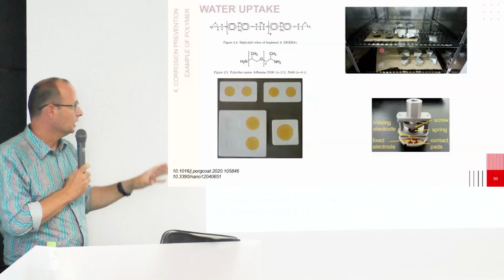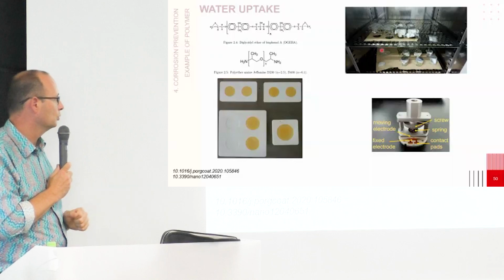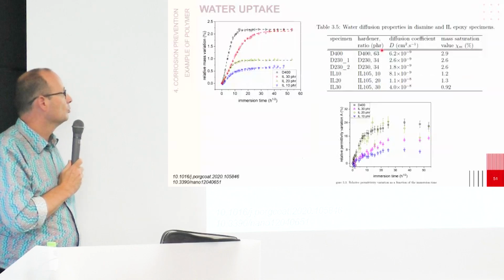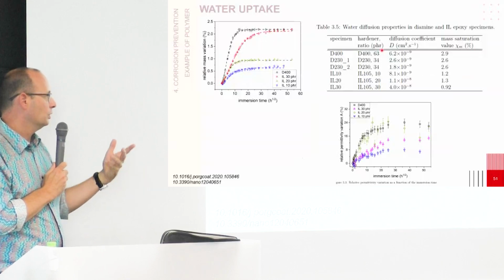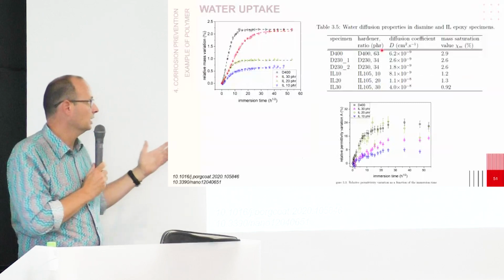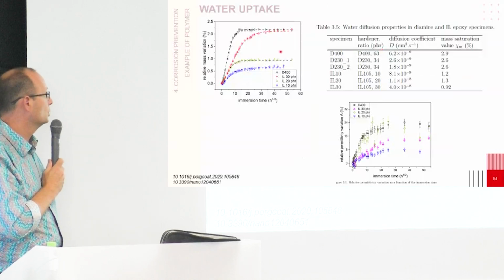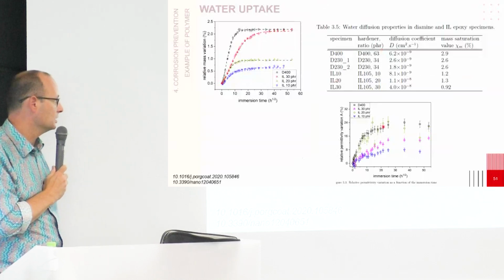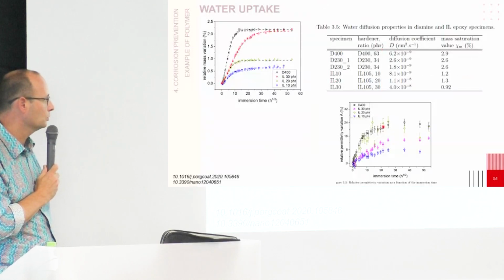In this case, it was capacitive measurement, so using the evolution of the dielectric properties of the polymer. What were the results? So here the question is, can we have a reliable technique to evaluate the water quantity in the material? The first graph, which is on the top, is a mass evolution of a coupon. And at the same time, our young colleague was performing capacitive measurement to get the relative permittivity evolution of the coupons with time.